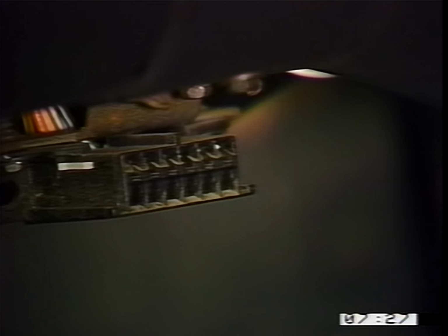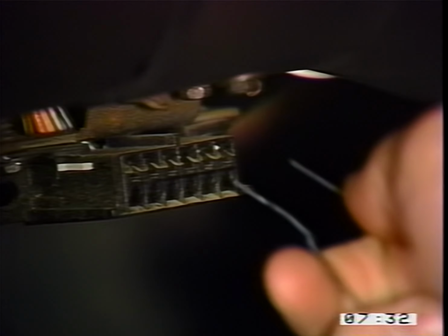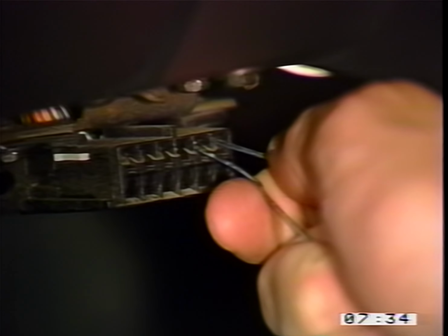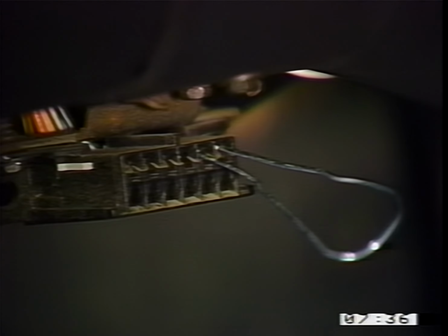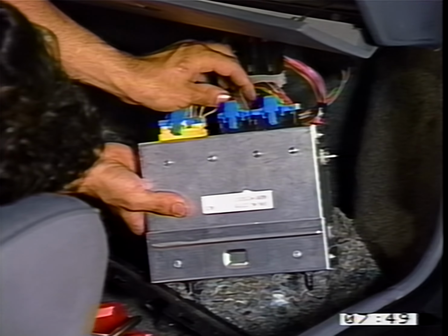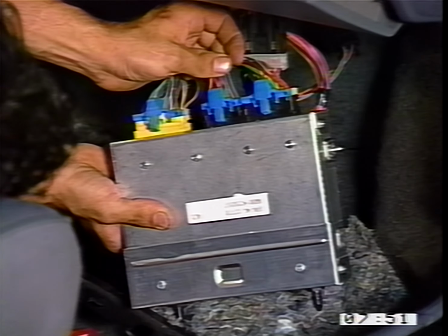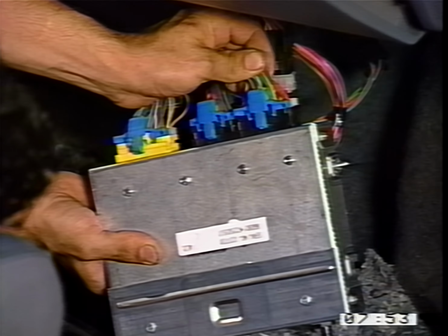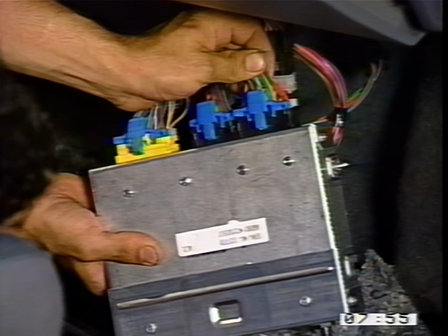A standardized 12-pin connector is found on 82 and later applications. The jumper is connected between pins A and B. The upper right-hand pins trigger code retrieval. On earlier applications, a single male spade is inserted between the open terminal divider on the last 2 pins to initiate ECM code retrieval. Both techniques accomplish the same thing, taking a lead from the ECM to a known good ECM ground.